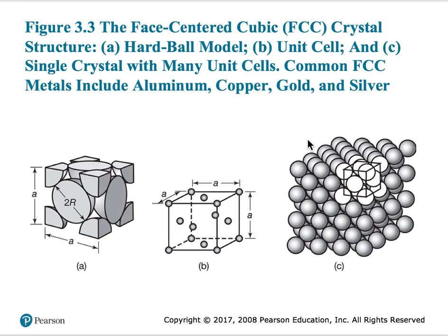The face-centered cubics have atoms at the center of the faces as well as at the corners. Common materials are aluminum, copper, gold, and silver, or even nickel for that matter. They are much better in creep types of applications, but they are also good for fatigue, and they are also good for deforming into different shapes and forms that you want for different applications.